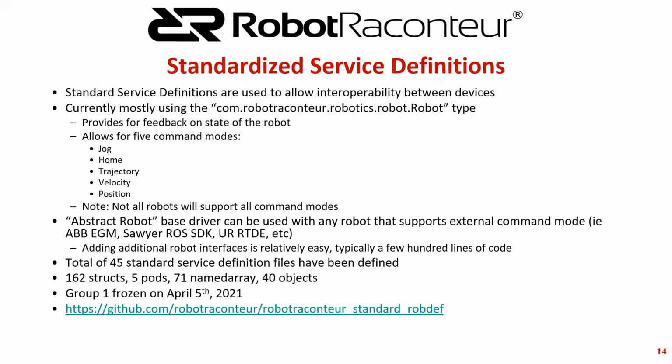Our current project is looking more into using the onboard motion controller. So we have a motion program execution that we're working on right now to basically send down a binary instruction file, and then the robot will run that file using a kind of customized interpreter written in Rapid. So that'll be available in the next few months. The goal being that you switch between the onboard motion controller and the external position control.